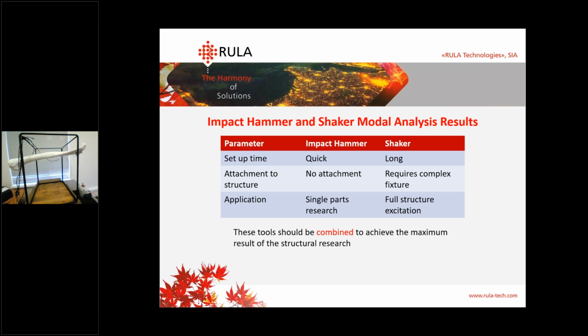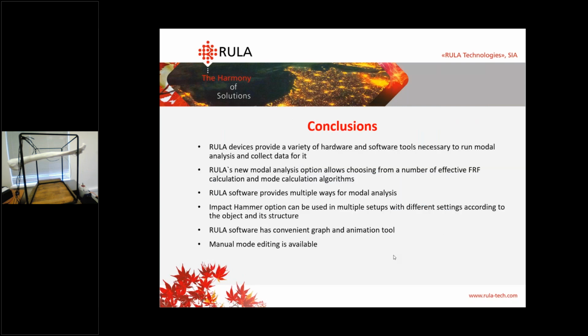So the best way here is to combine these ways. Like we had higher frequency range with the hammer, but the range from 200 Hertz up to 1000 Hertz was covered with a shaker. So today we discussed our software tools which are necessary to run modal analysis and collect data for it.